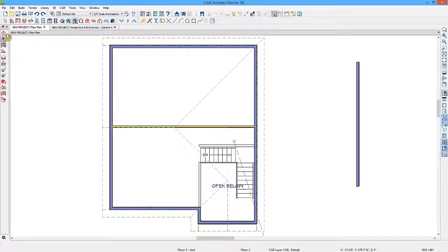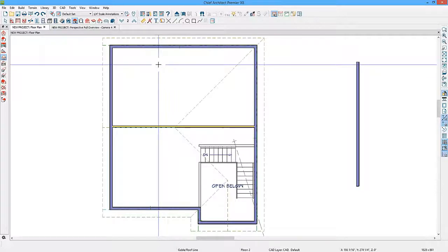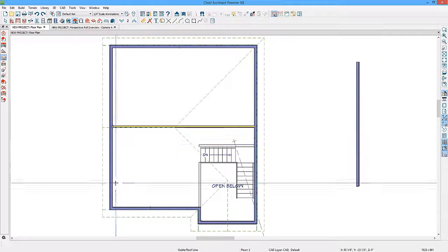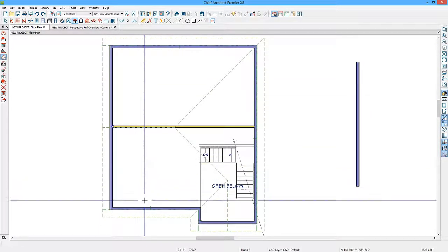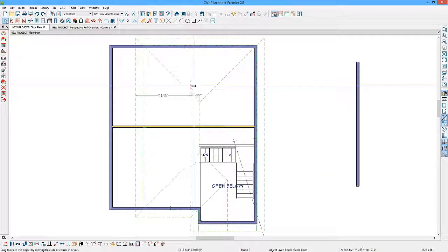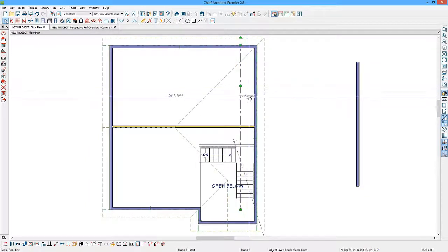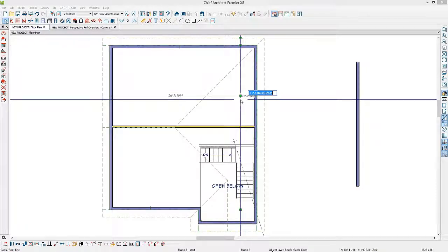We'll go back to our Roof Tools parent tool and use the gable roof line. With this, what you're going to do is draw a line outside of the wall where you want the gable to form. But I want to make sure that it's the exact length of this wall. So I'm going to draw this line from the outside edge of this wall all the way through to the outside edge of this wall, and then select that line and then move it over towards this wall and use my temporary dimension. I'll click on this temporary dimension, and I want this line to move all the way to the edge of the wall, which would be to 0 feet, and then past the wall.